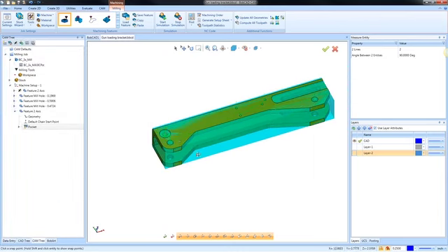Another thing that I want to look at here, like these holes, this is like a 5906. I don't know whether it's a metric one converted to inches, or if that's like a specialty tool's hole size. I'm not really sure, but what you may end up doing with this is drilling it with like a 1/2 inch end mill and then finishing it to size. Yes, Mark, we'll get into spring passes in just a second. So what you may do here is drill this to size, but then you may either ream it or you may circular interpolate it. And that's the next one I want to look at here.